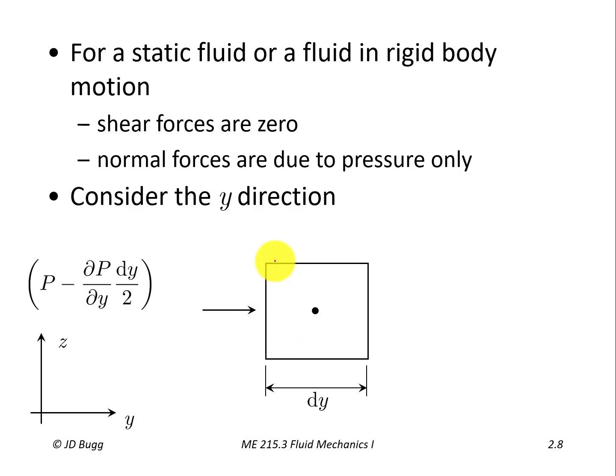So that's fine. What we have so far here is the pressure on this face. Now, it's not the pressure we want, it's the force we want. So we need to multiply that pressure by the area. And remember, the area of this face will be dz, the distance from there to there, that's the z coordinate, and dx is the distance in and out of the screen. So there's a little square there, and that's its area. So pressure times area gives the force.